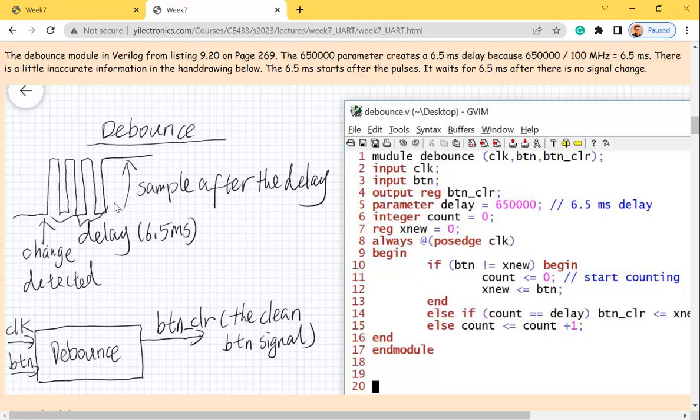Okay, you push it one time and it oscillates like 10 times sometimes, right? It oscillates 8 times the next time. So when you push once, you want to send one letter, but instead it sends 8 letters, and next time you send 10, right? You just couldn't control it. So you need a debounce circuit.